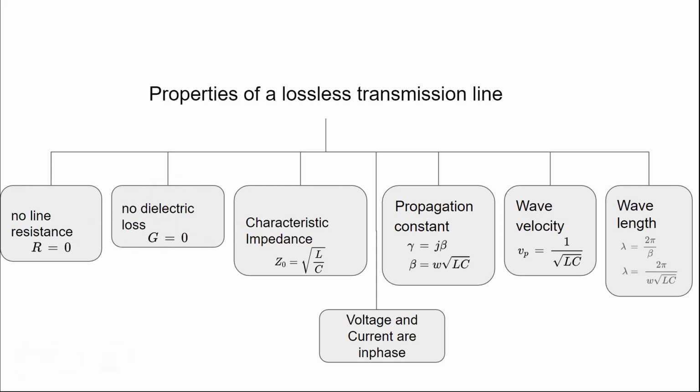That means the stray currents across the two conductors in the transmission line are almost negligible, and therefore the dielectric is a very good, almost perfect dielectric, right? It does not conduct current between the two conductors, and it prevents stray currents from occurring, right? So we are considering a scenario where we have good conductors and good dielectric material in the transmission line.